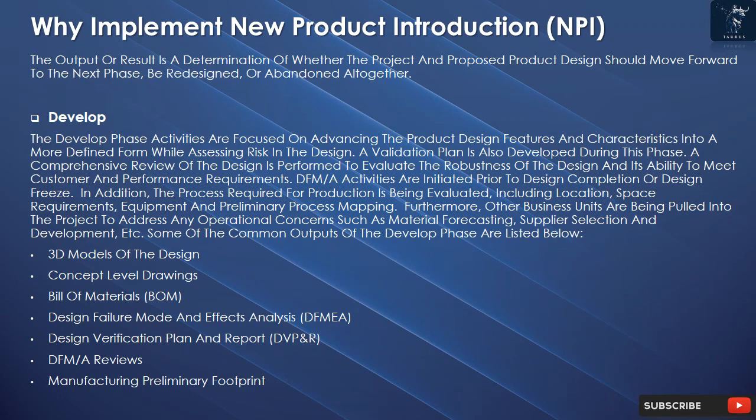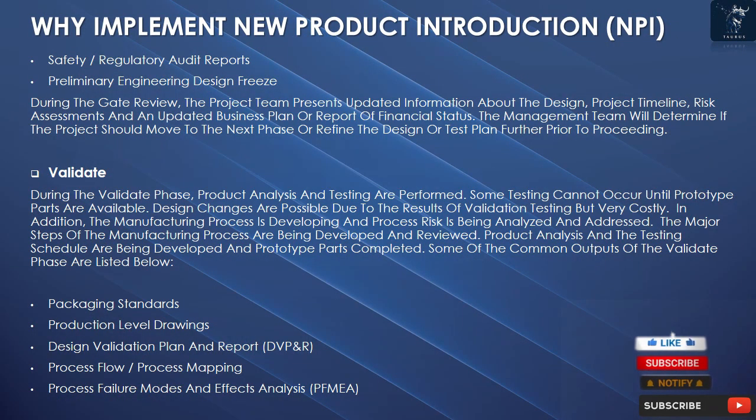3D models of the design. Concept level drawings. Bill of materials, BOM. Design failure mode and effects analysis, DFMEA. Design verification plan and report, DVP&R. DFM/A reviews. Manufacturing preliminary footprint. Safety/regulatory audit reports. Preliminary engineering design freeze.